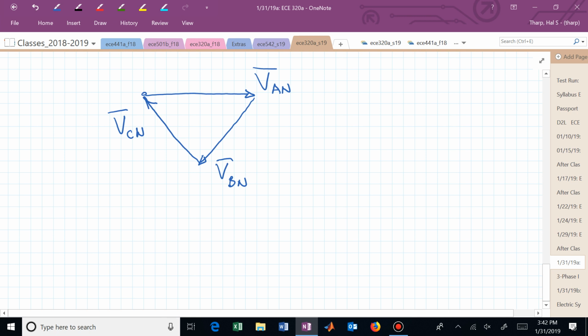Basically the phase depends on where you draw the line in the sand or on the tape or on the floor to define t equals 0. So if it's just plugged into the wall and you see this on the oscilloscope, you're going, okay, where do I define t equals 0? You could then say, I'm going to peg it right here, and that could be right where it's peaking, for example, and now everything is relative to that.